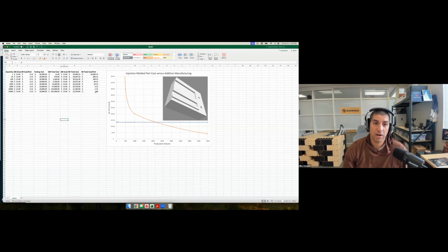And so there's kind of that sweet spot with 3D printing to say, okay, hey, for this part, we can think about this as a viable cost technology up to about 2,000 components or 5,000 or whatever it may be, depending on your kind of overall existing manufacturing cost. So that's how I start to think about this, and where you can start to bring in data from the 3D printing, these quoting services, or get parts produced, but also kind of use it to inform your own internal capacity for thinking about alternative manufacturing pathways.